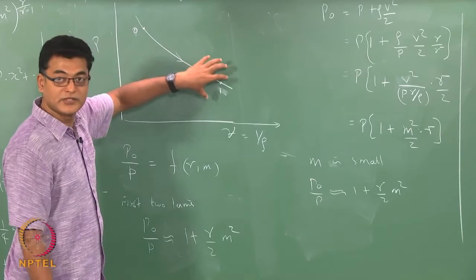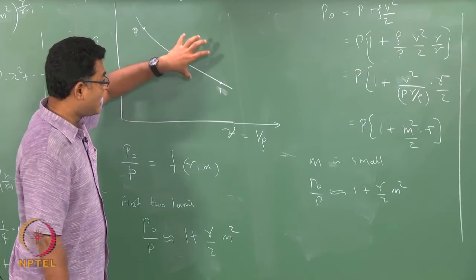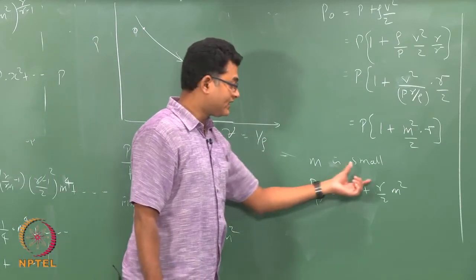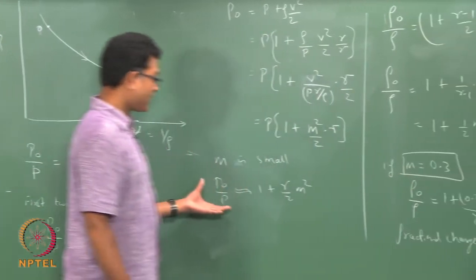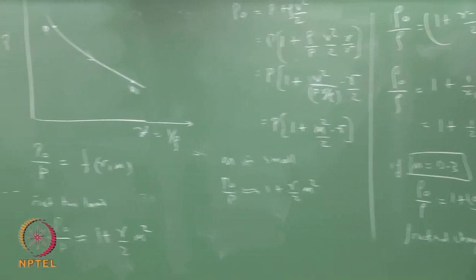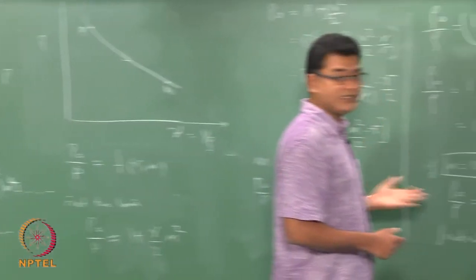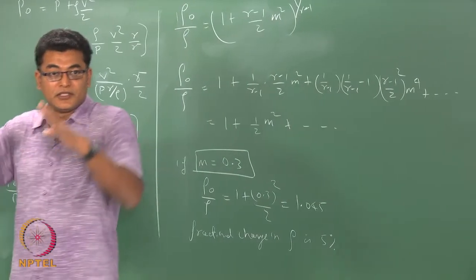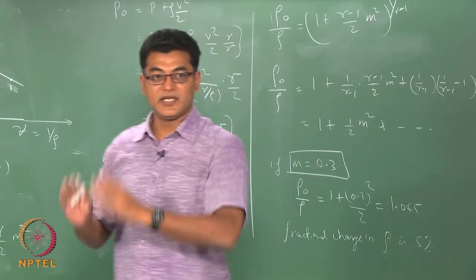To get that Vmax, some energy is taken from the total energy content, and in the process the pressure changes. If the Mach number is less than 0.3 it is incompressible, greater than 0.3 it is compressible, where we need to use the full set of equations. Okay. That is how the properties change during the expansion process, where the total energy of the gas is producing some kinetic energy.